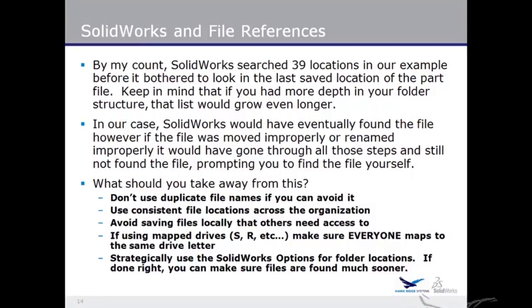So if you are sharing data across your organization, it's a really good idea to make sure those files are saved to the server. Sure, you're going to take a little bit of a performance hit because you have to save across the network, but ultimately, if you're saving files to the network and the references are getting written to network locations that everyone can see, you're not going to open files and see it down in the lower left-hand corner searching for something on someone else's drive. It's just a little consistency thing that you can maintain.